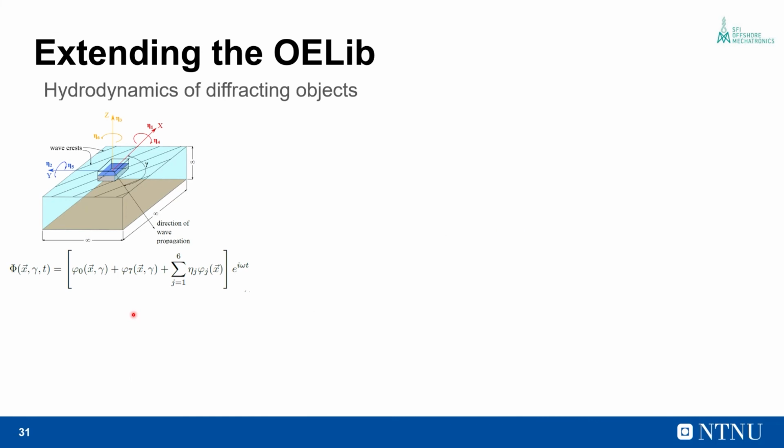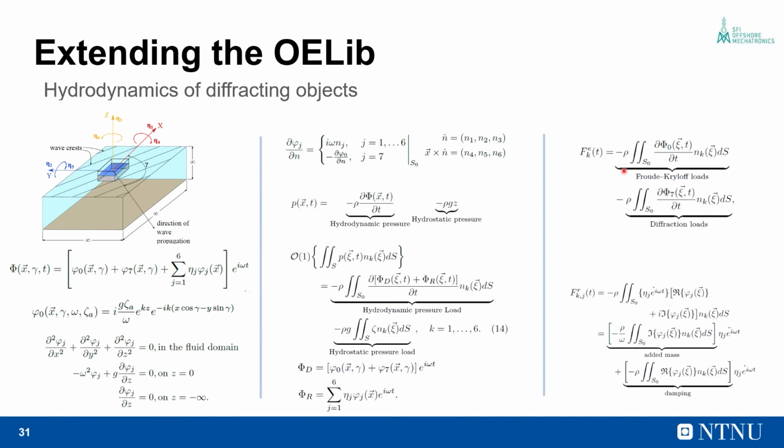In order to extend the ocean engineering library by including component models to simulate the hydrodynamic response of larger diffracting objects, we need to solve the wave structure interaction problem in its entirety. That means we have to solve the diffraction problem to determine the wave excitation loads and the radiation problem to determine the added mass and damping loads.